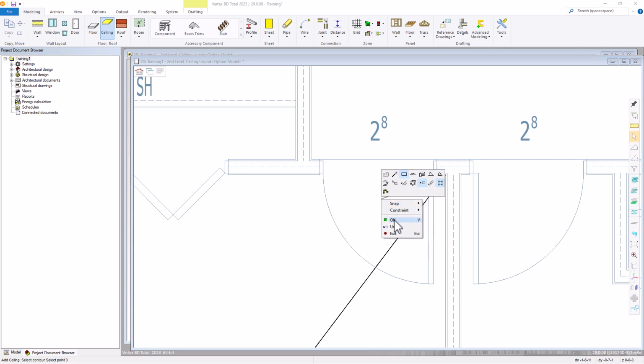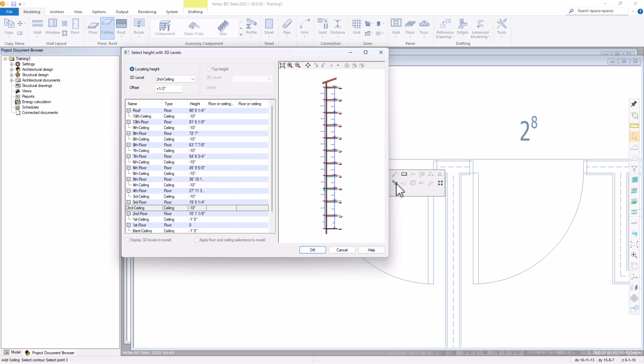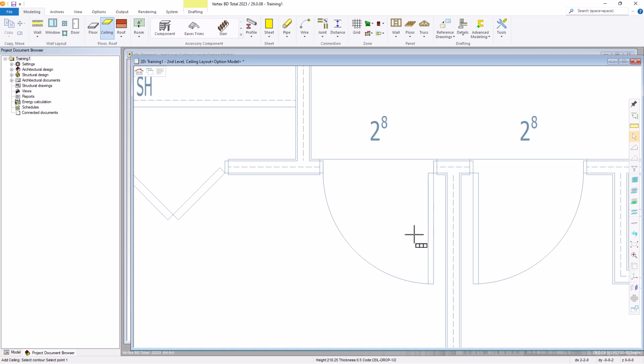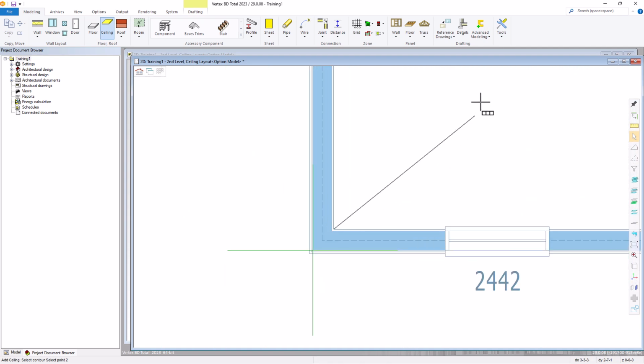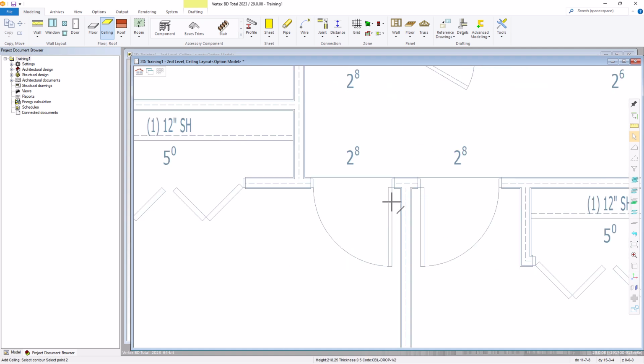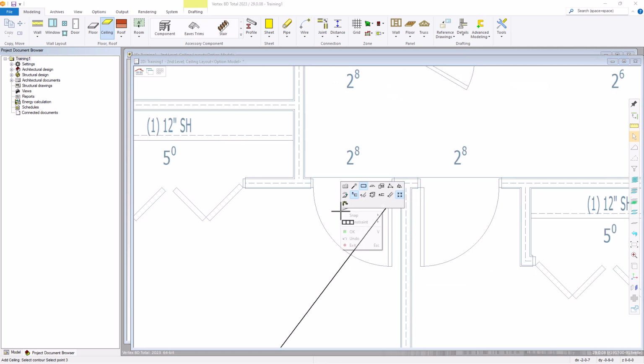Right click. We want to make sure actually that we are set to horizontal area by top plane. That way the plane that we're selecting is the top and the drywall extends downward towards the room. We also want to make sure that our offset is set to 0 and select OK. Select that again. Click that point, back to that point. Now V to confirm.